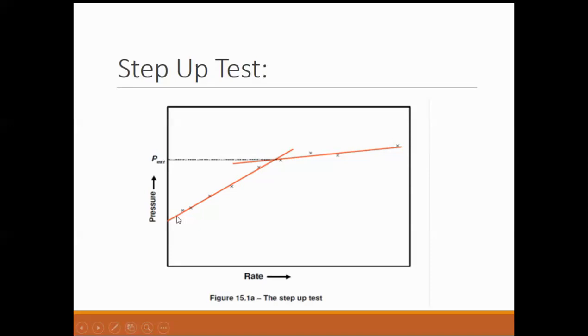Rahul Pawar is asking what the flowback additives are and how they work. Flowback additives are basically chemicals whose composition is not revealed by the companies, but they change the wettability of the formation, and basically they adjust the surface tension between the formation rock matrix and the fluid, so that it can be recovered easily.